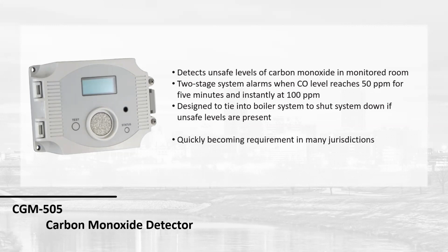I know NFPA has talked about it, but the point is this device is designed to specifically interlock with mechanical appliances. We have a two-stage system. We have two relays basically, so it can either run as a single appliance two-stage system or two appliance single-stage system. We can also extend it with an expansion board up to 15 appliances, or you can use it in conjunction with a master gas valve.